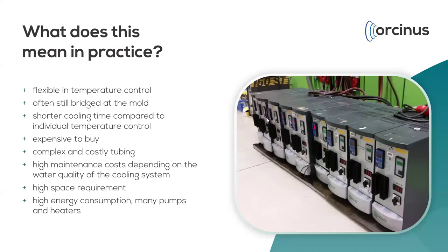You need a lot of energy to run all these TCUs. And so it is, in our opinion, not the best solution to help you to have a stable process. Because every time you change the mold, you have to set a new temperature for each of the TCUs, which makes it not very comfortable.